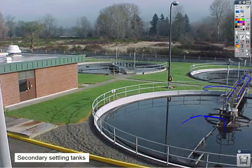So that while the water is passing through this settling tank, all the little particulates, any sediment that was on the sludge will settle out. So by the time the water gets to the edge and drips over, it's been cleaned again of any particulates and sediment. So you'll see water pouring over the side here, and that little white dot is water actually pouring over and going back towards the last stage.